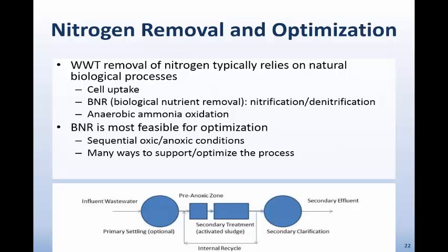Nitrification requires, among other things, oxic or aerobic conditions, in other words, aeration. Bacteria convert ammonia into an oxidized form, primarily nitrate or NO3, and then under subsequent anoxic or unaerated conditions, the nitrate is biochemically reduced to dinitrogen gas, which is harmlessly released to the atmosphere.